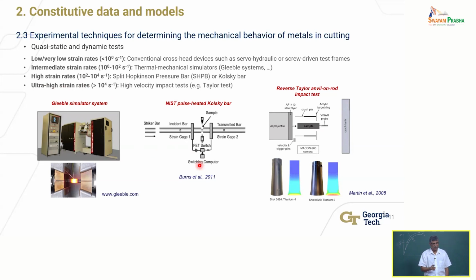Historically, most of the models people have built to describe material behavior for machining simulations, even the commercial software you might buy, use a combination of low strain, elevated temperature compression tests, simple compression of a block of the material that you're trying to simulate. They'll conduct experiments at different temperatures, by heating up the part, compressing it till it fails, getting the stress strain curve, and from that extracting the yield strength, right? Getting all of that data at low strain rates, doing those high temperature experiments.